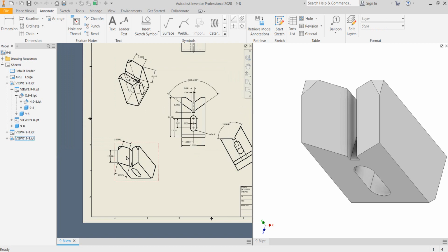Because they're not used to manufacture the part. They're just used to check the part. You can make it a reference dimension. It wouldn't really be an inspection dimension either.